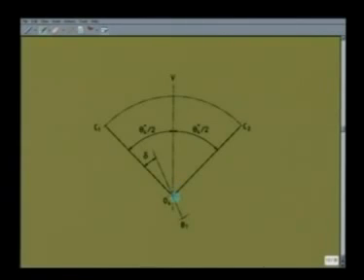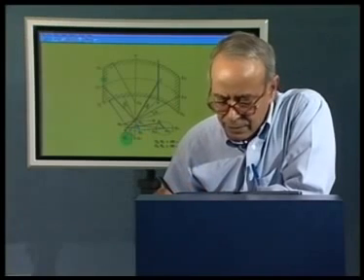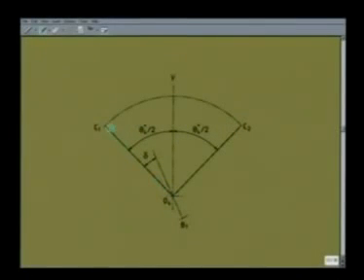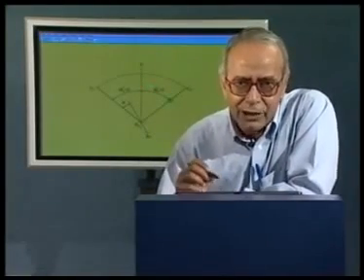We have already seen B1, which is the extreme position of the link O4B, which we have obtained earlier. Now O4C1 must be like this to make the field of wiping symmetrical, because now I have made O4C1 and O4C2 symmetrically placed about the vertical line, at an angle theta 4 star by 2 and theta 4 star by 2, because theta 4 star is entirely decided by all the link lengths, which I cannot change.